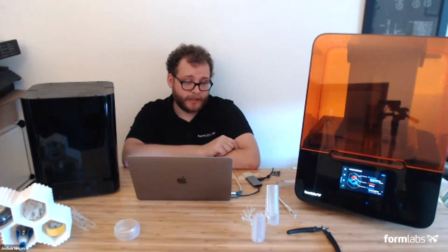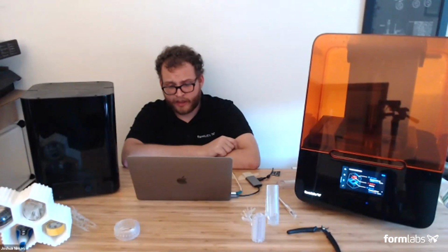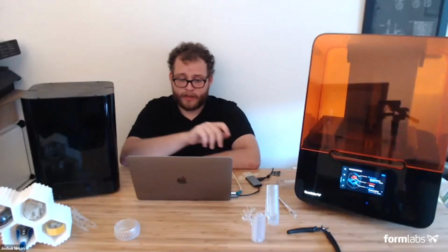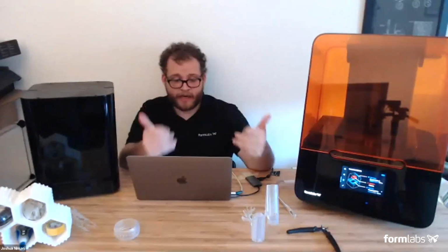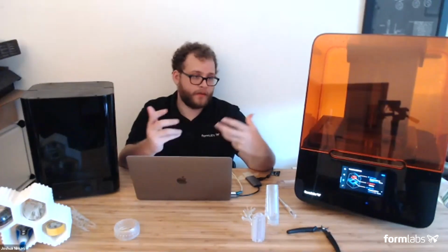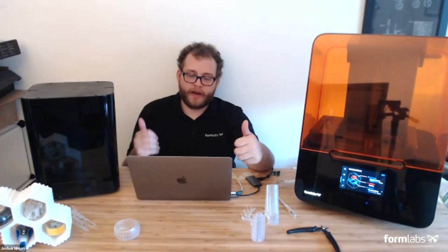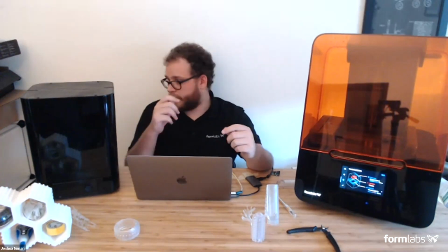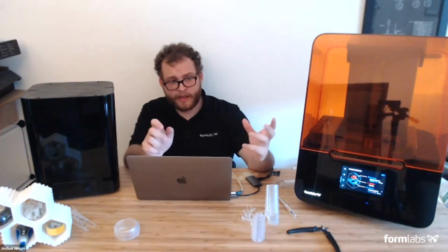And my solution there is always to positively run IPA over the surface of the part, either safely with a squeeze bottle back into the Finish Kit, or with a syringe if it's small channels. I find, not just relying on agitation or the impeller in the bottom of the wash or the agitator basket in the Finish Kit, if that's not enough, some sort of positive flow of IPA, really spraying down the part in a safe way, obviously, it's flammable, makes my life a lot easier.